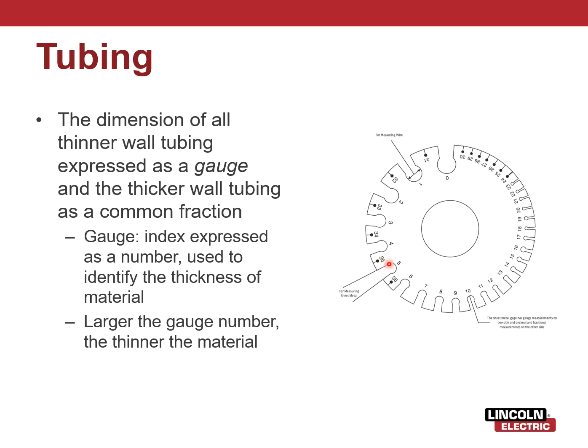I mean, you'll know if it's the right size, what gauge. And if you flip this over, it'll give you the equivalent of whatever gauge in the form of a fractional decimal. So for instance, 12 gauge is going to be 0.105, and then 10 gauge is going to be 0.135. So both of them are right around an eighth of an inch, but 10 gauge just over and 12 gauge a little less. But you could use this gauge if you had no idea what you were looking at. Maybe you got a sheet donated and there was no color coding on it, and you wanted to not guesstimate the thickness, then you get one of these sheet metal gauges, put it up on there, and boom, now you know.